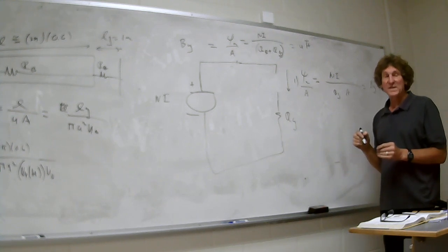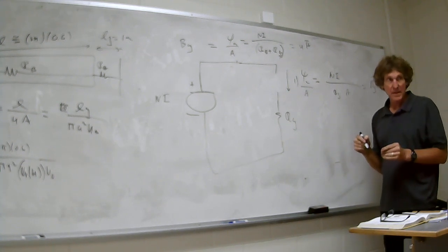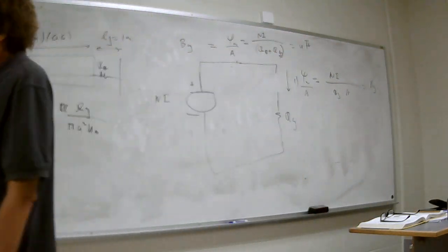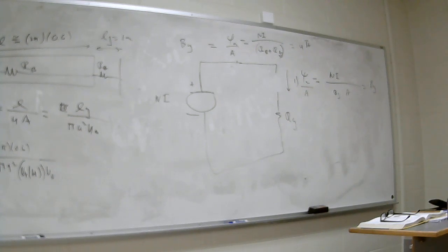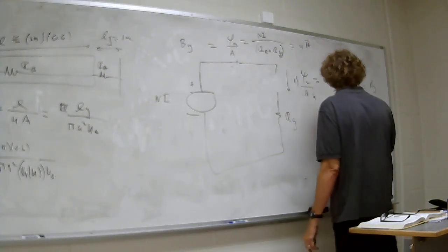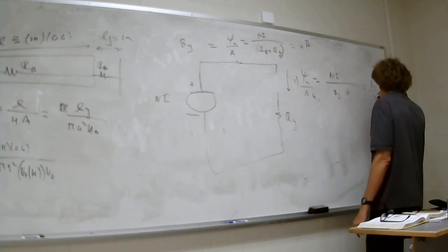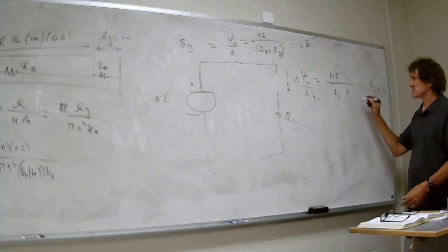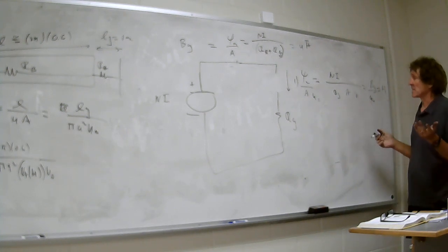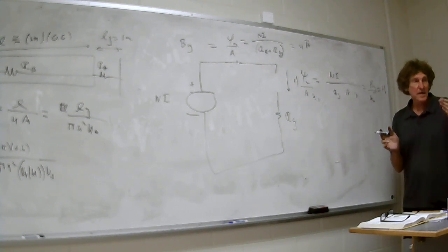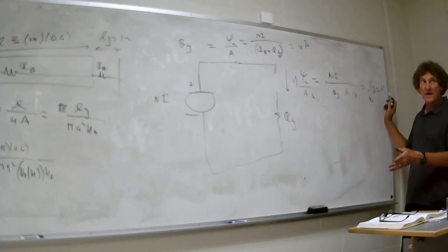Now, once you have this, you can get the H field, right? Is that what we're looking for? Now we're going to use this because we've got to iterate. We've got to go back over here to this plot and see where H is. We've got to add some more. So now if we divide this by mu naught in this case, we're going to get our H from the first iteration, H1. Are you with me? This will be divided by mu naught. So if you do, I don't know what it comes down to, but you follow me on this? If you look at his solutions, he's going to do something like this. He's going to iterate to the value. You're going to get this first value, okay?